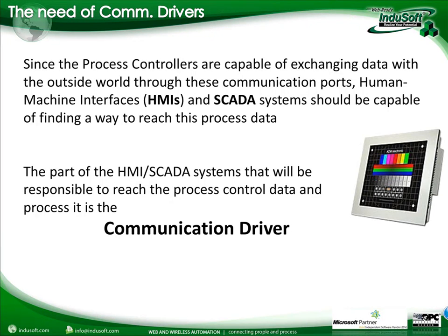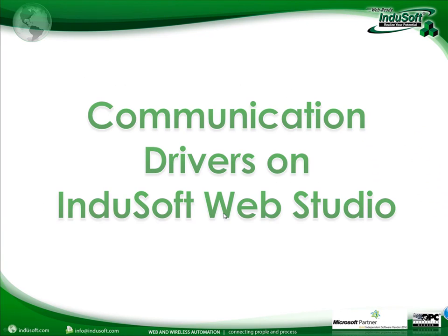And the specific part that's going to be taking care of sending this data out, of reading this data from the PLC, or more precisely, communicating through the communication channel with the process controller, is the part of the software called the communication driver. Okay? So, the communication drivers on InduSoft Web Studio.